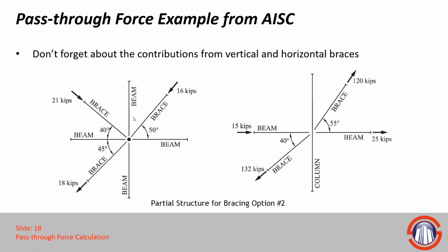We're looking down in plan view, and this is an elevation view. So we can see that we do get contributions for specific joints from the bracing as well. That wasn't really easy to illustrate in those last images. So I wanted to include those as well to see that there are some forces coming from the braces and from the beams, obviously. So you can get an idea for what those forces might be.